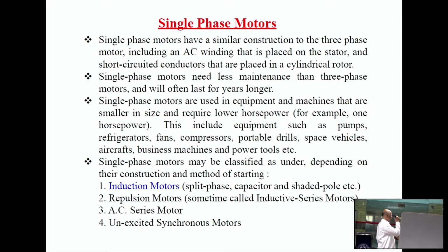So single phase motors have a similar construction to three phase motors. Any motor means stationary part and rotating part, stator and rotor. Because it is single phase, it will receive the single phase AC supply, so the AC winding is placed on the stator and the short circuited conductors are placed in the rotor. The principle of operation is almost similar to our induction motors.